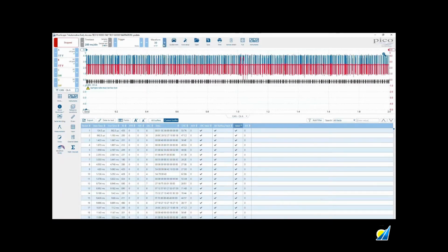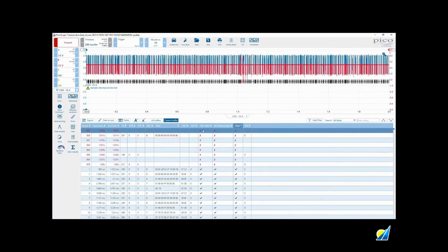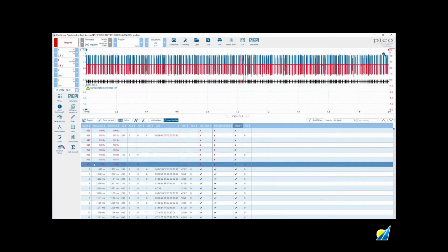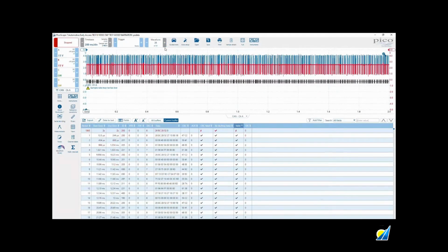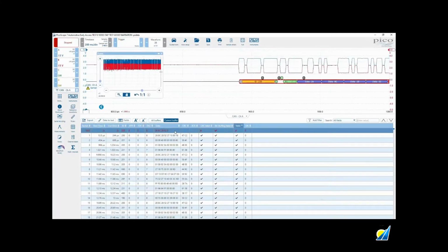Let's go to buffer 30. Now ordering by invalid, there you are. You see it's listed 925 to 978, so I think there's 8 in total that are in error. And moving on to buffer 31, it has found one here, and why is that? Let's double click on that and that will take us straight to the packet of interest.